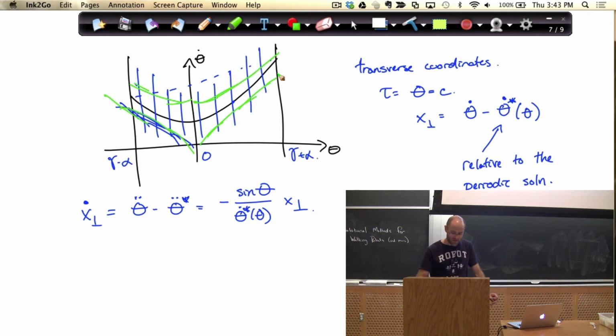The major stabilizing event is at the dissipation, okay, is at the impact. But even though this coordinate looks to be diverging and this is contracting, I can still find a Lyapunov function which is going downhill all the time and has a periodic solution, okay? So for the system to be stable over the period is different than it to be stable always, at every instant in time, right? I can go away from my trajectory and come back, and I can still find a Lyapunov function that would prove that. Okay, that's a very important idea.